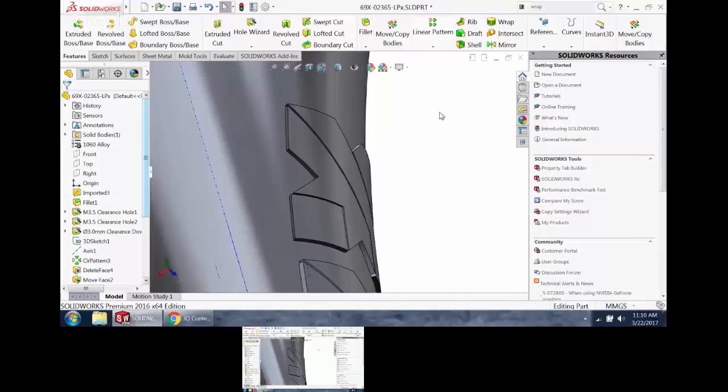And in the end, it wasn't worth my time, right? The molders are going to add draft and then machine the molds. And that typically is true, but you can put it on there to give them less rework time or less finish time. But that's how I would do it. I would use the parting line and then pick the edge of that, and you have to do each edge pretty much at a time. Can't pick a surface and draft on surface.